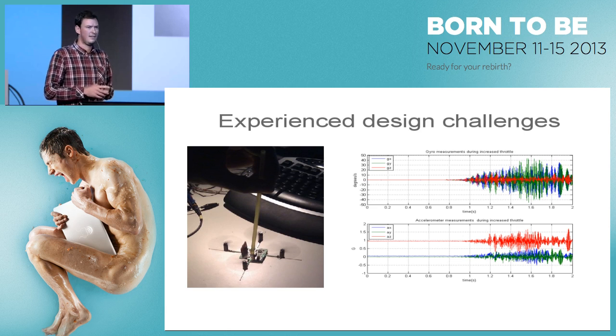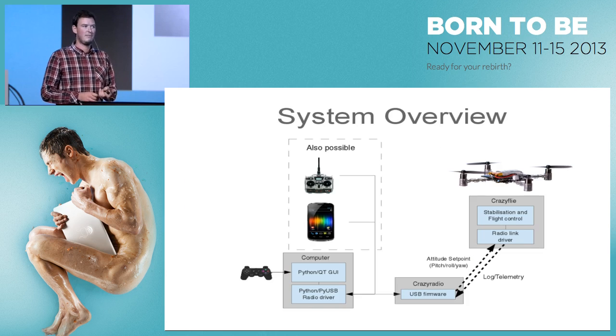It was some conversion from integer to float, but we couldn't find it until we came up with the idea to attach a straw to the top of it, so we can restrain its area of movement. And after that, it was flying a couple of hours. So a good debug technique is a must.